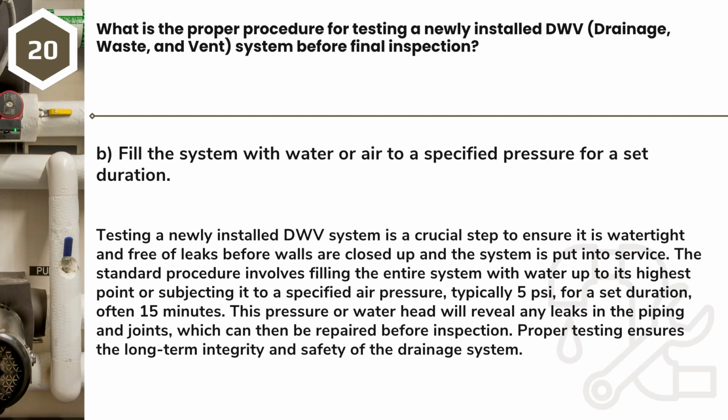Answer: B. Fill the system with water or air to a specified pressure for a set duration. Testing a newly installed DWV system is a crucial step to ensure it is watertight and free of leaks before walls are closed up and the system is put into service.